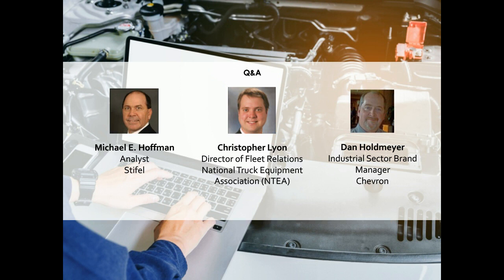If you want to look for that fuel economy, you might be looking at 10W30 for a majority of your fleet. If you're not so worried about that, you're working in a hotter environment, you might want to stay in a 15W40. So some things to discuss with your supplier and ask them some serious questions about what you're doing and what their recommendation would be and how they can meet your requirements. Thank you.